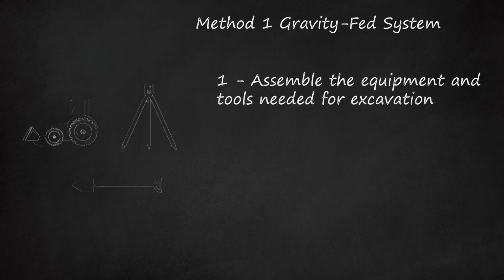Hammer drill and bits, to go through wall if necessary. Hydraulic cement, to seal around pipe if going through wall. Shovel. Inch and a half washed stone, quantity depends on system size. Tape measures, regular and also at least a 100 foot tape. Septic fabric, cut roll to 3 feet long or so. Septic tank and risers, concrete or plastic if allowed.